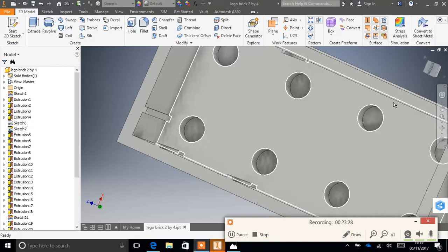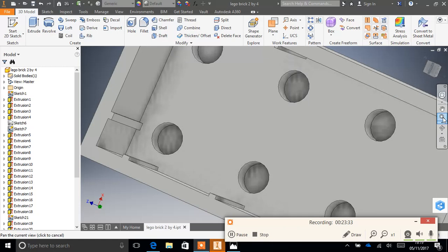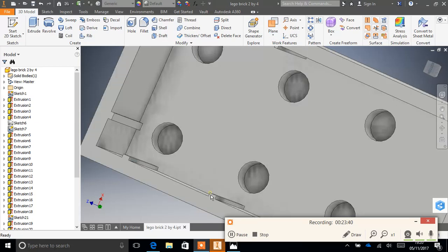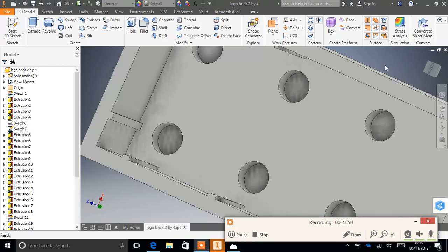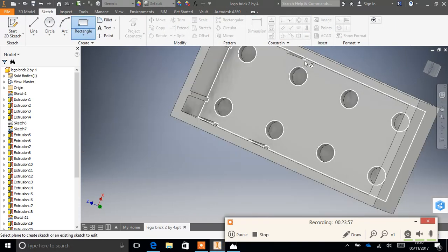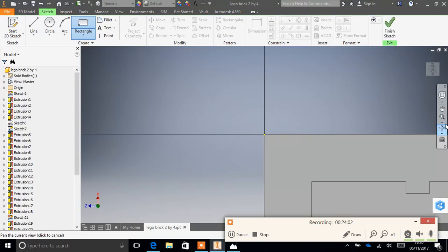So that is an alternative way of doing this, but I'm stuck with what I'm doing now. If any of you copied my measurements when I was doing the first few of these bits, I actually had the wrong measurements, and therefore they weren't flat, so they didn't join up like that. I hope that you haven't copied me, because if you have, you're going to have to go back into those and change them to 8mm, because that's how far it really needed to extrude. Anyway, I'm still continuing with this.